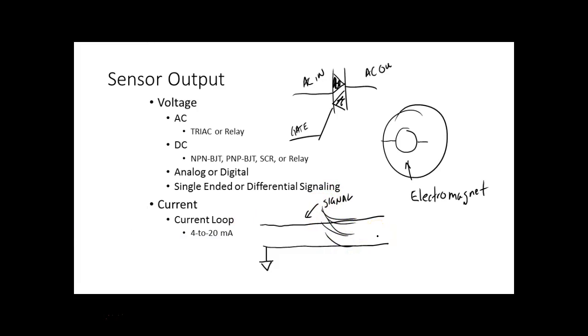And this is why the current loop in industry was so popular for so many years. The only thing that voltage would interfere with is if our channels were extremely high resistance. So if this input over here was like 10 megohms, and then I put that pulse in there, there'd be almost no resistance out there to load that EMI, and it would cause the voltage to change.